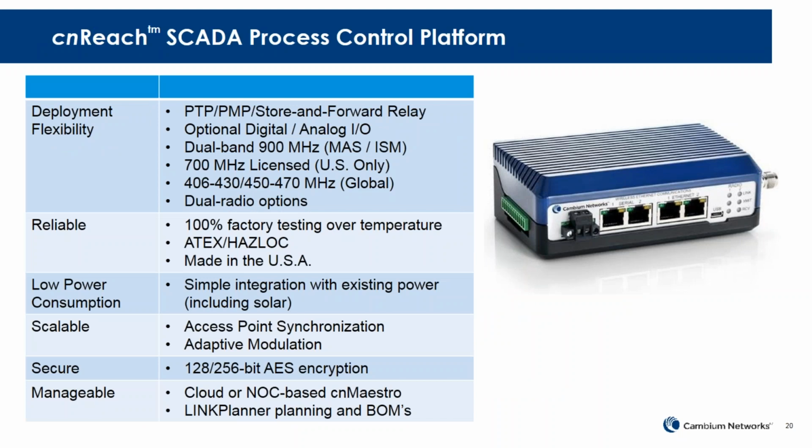So the things that are important when you build a wireless system for process control, I just hit these at a high level, but you need to have flexibility. Remember I mentioned that you don't know exactly where these locations are going to be ahead of time. So you need a system that can operate in different ways, whether it's point-to-point, point-to-multipoint, in a very harsh environment, or depending on what frequency you want to use, you might have access to different spectrum or different channels to use.